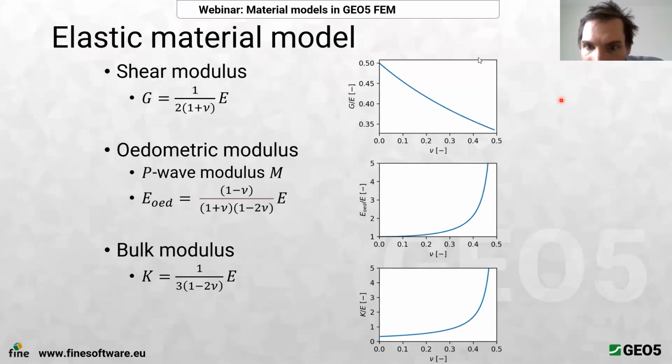So hello, can you recommend in what case it is advisable to use geostatic stress calculations and when the K-naught procedure? Okay, so when to use which type, or how to generate this geostatic stress. I would generally suggest to go with the default value, which means the calculation of the geostatic stress and not the K-naught procedure.